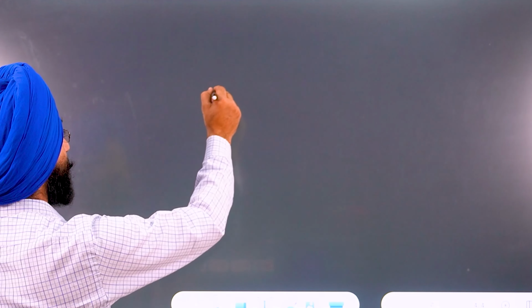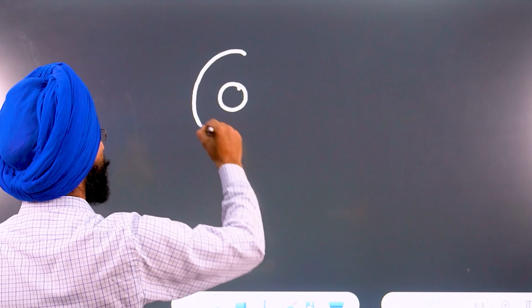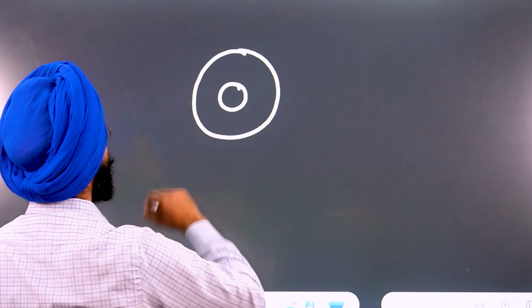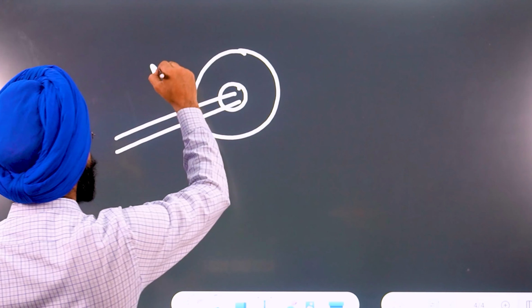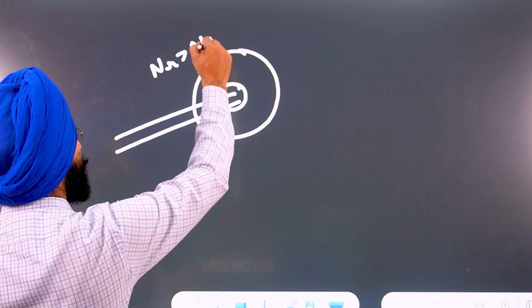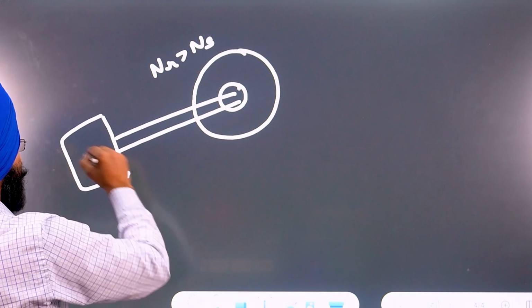So what is the next case? In this particular phenomena, let us say we are having an induction generator. This is the rotor, this is the stator, and we move the rotor greater than the speed of stator RMF with the help of a prime mover.